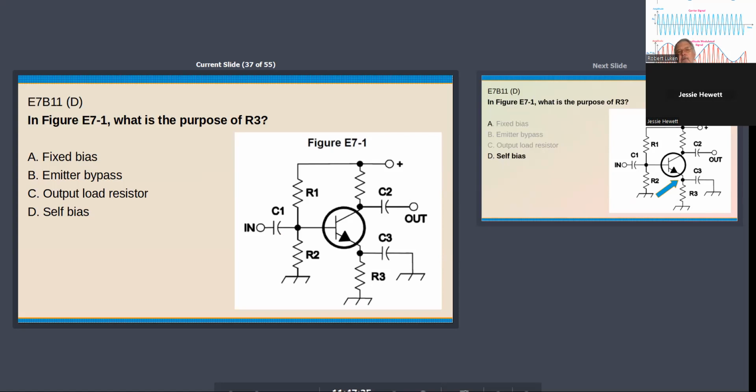Yes. Because remember that the transistor is going to have a gain of maybe 50 to 100. So for every microamp going into the base, you've got 50 or 100 times that amount of current potentially flowing from the collector to the emitter.